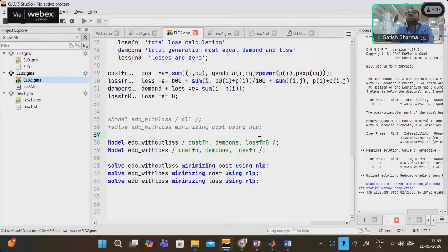We assume that this much renewable will be there, and the demand is also highly unpredictable, it's uncertain. So the renewable part is basically moved to the demand, giving net demand instead of the actual demand. We can perform the economic load dispatch for the net demand, and net demand is inclusive of renewable as well. So I think that should answer Satya as well.